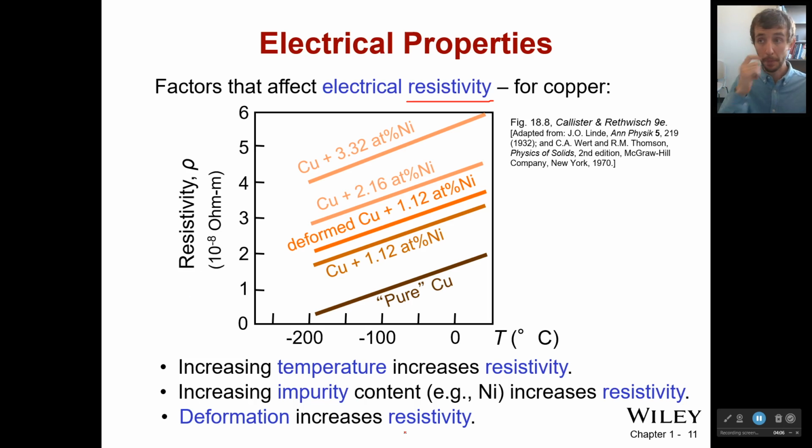It's because electrons need to flow through, and if there's some nice clear pathways, like you haven't bent it at all, it's just all these atoms right after each other, it's easy to flow. But as soon as you start bending that back and forth, those atoms pop out of the way, and it's just like having a bunch of cars in the middle of the street. You can't go anywhere. Traffic jam. You're having to flow around them. So less breaks, less balls in the way, easier for electrons to flow, so less resistivity.